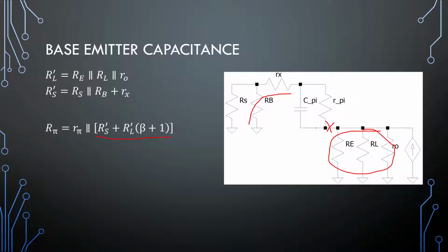See it as we make this ground for ourselves and we increase this resistor size and we move it in series with all of this right here. We place it in this position as an extra resistor. So then everything in series goes to ground. R pi goes to ground from this same position right here, and both of them will be in parallel with C pi. Okay, and that is the resistance seen by C pi.